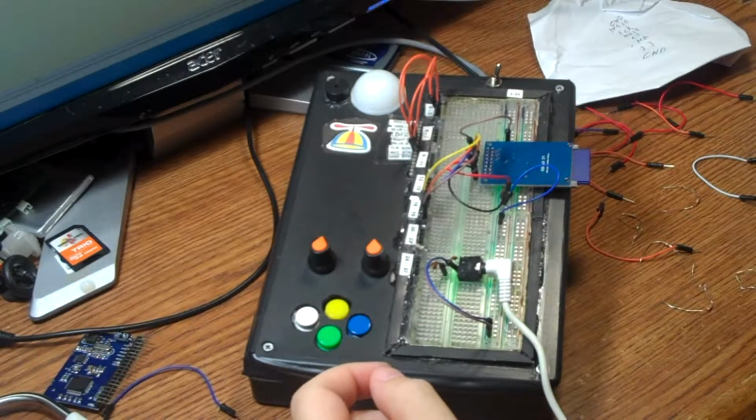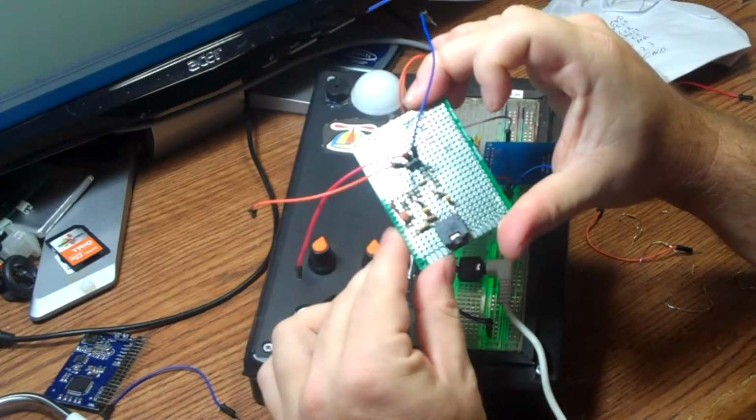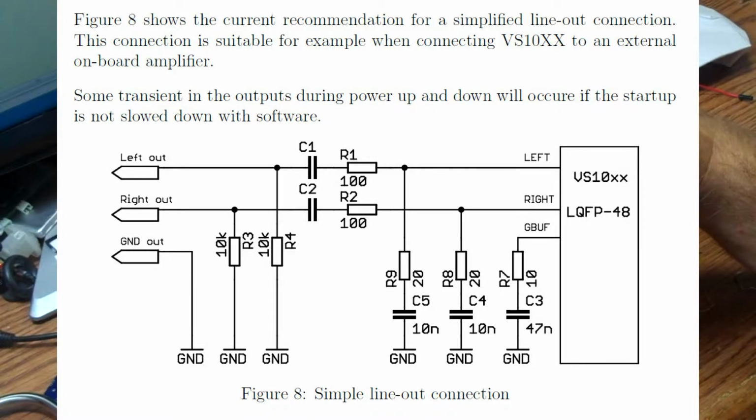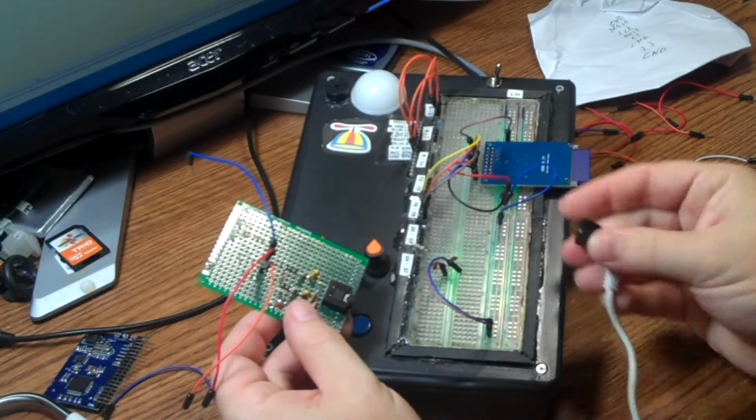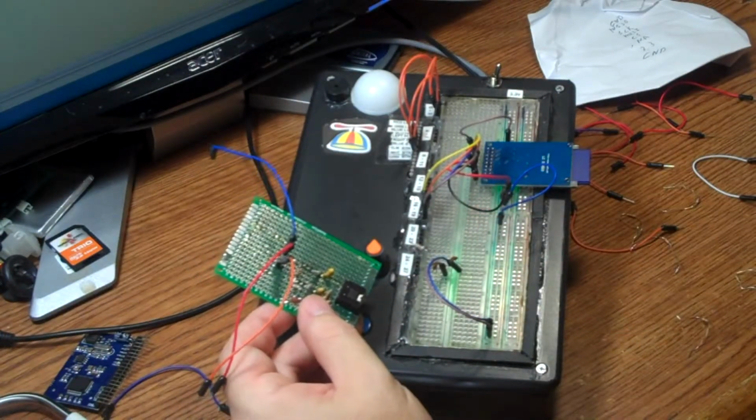I tried to go with this more complicated circuit I made for the original MP3 player card. Supposedly this was to shield it from a powered amplifier, and I ran it into there instead of this, and got lower volume, but I'm still getting hum.